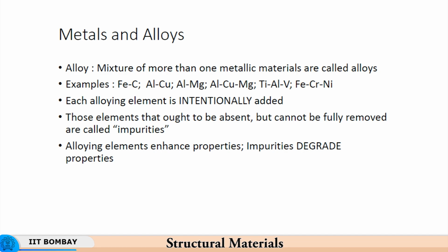One is, to start with, you do not need a great volume of the material to do the same job, to withstand the same load. So, the relatively smaller volume of material is able to withstand that much of structural load, plus because of the lower density, the mass, the weight of the material that is required gets reduced, because first thing is your volume is reduced, and furthermore you have used material of lower density. So, you have double benefit by adding elements of lower density to elements like aluminum.